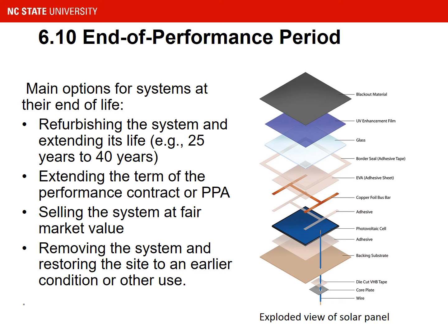Another item that I'd like to talk about through recycling is the battery systems. It can be expected that batteries will be replaced 2 or more times during the life of a typical PV system. They just don't last as long as the PV modules. Currently, recycling protocols for lead-acid batteries are robust and executed regularly due to the monetary value of the materials in the mature processes. Recycling of lithium-ion batteries is behind when compared to lead-acid batteries, as the monetary value for the materials and labor-intensive recycling process have not gained momentum.